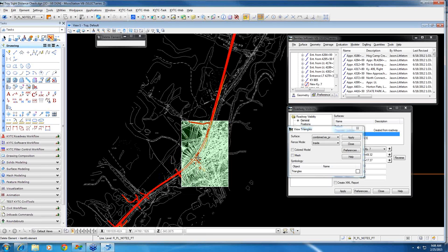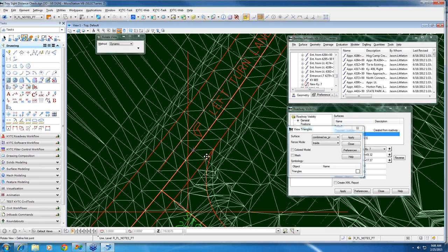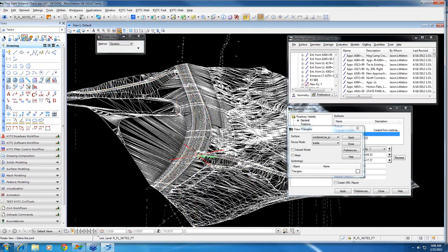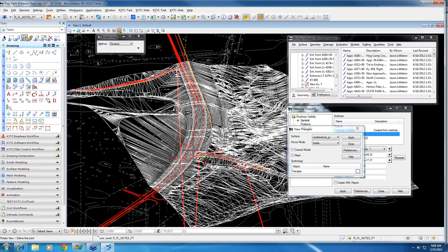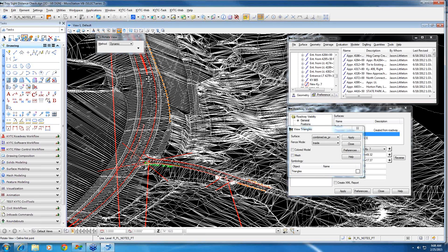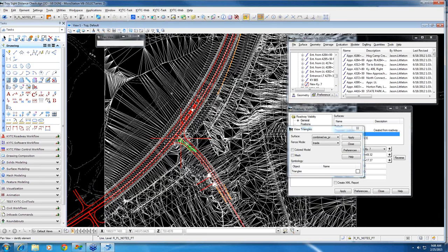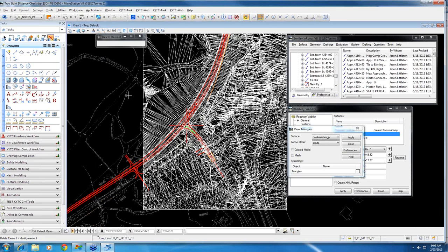And these tools really just freak out when you start crossing the boundaries. So this is the intersection that we're going to be looking at in a few minutes, but right now we're just looking at the corridor. You can see we've got the cut model here and the fill, and then when you get outside of the corridor, you've got the survey data. So that's what I'm talking about with a merged surface; that's what you need it to look like.